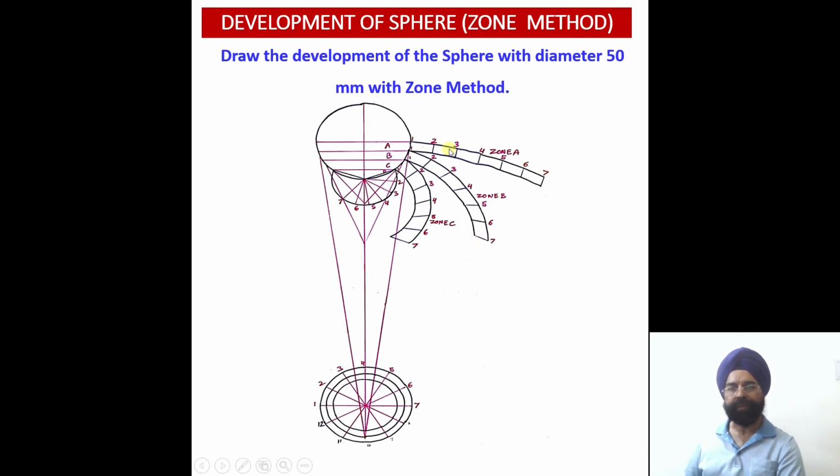Over here also 6 segments have been shown, so we could have continued with the remaining 6 segments, but the procedure remains the same. You can see I have divided this into 4 segments, and the 4th cone intrudes into my top view. So that is why a large distance should be kept between the 2 views over there.